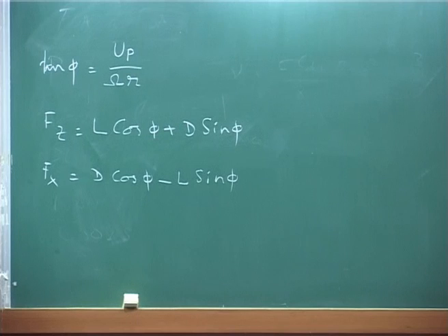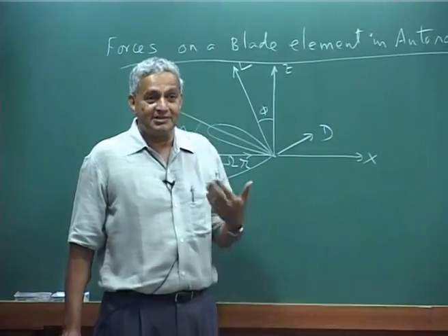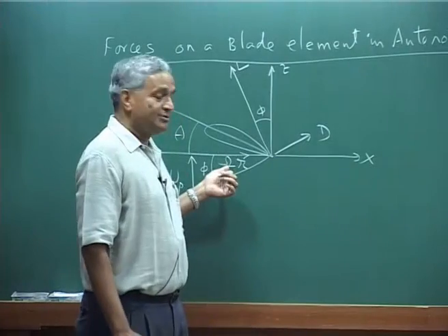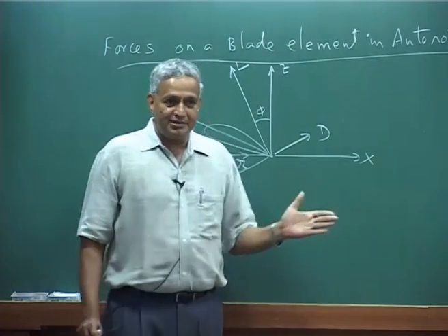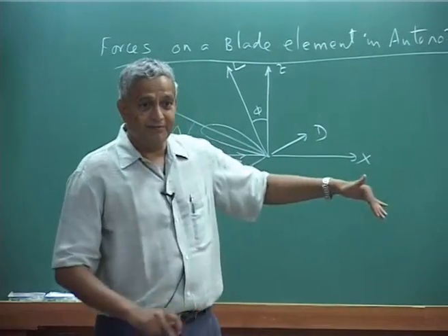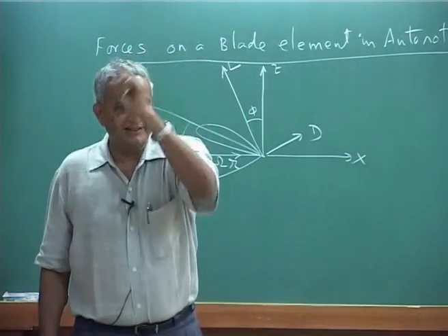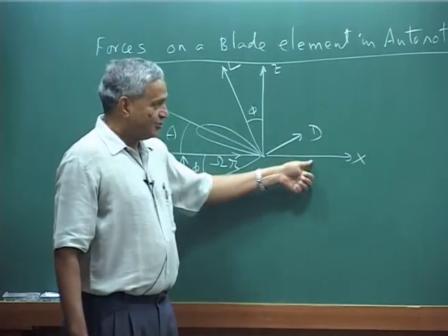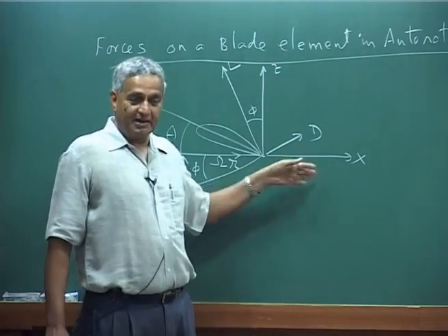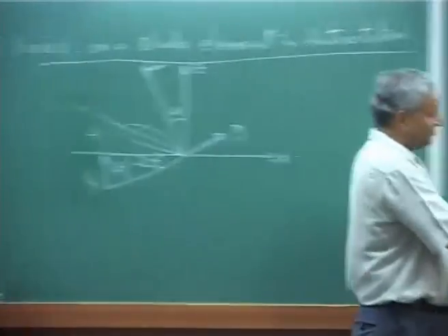Let us define the angle phi where this is 0, because if Fx is 0, please understand, initially the rotor is rotating because the power is coming from the engine, and that section is rotating with the omega r initially. Now, the engine is shut off or the engine has failed, so the engine is disconnected from the rotor and this is still rotating. Now, what will happen? You will have a descent, you will generate an Fx. If Fx is positive,